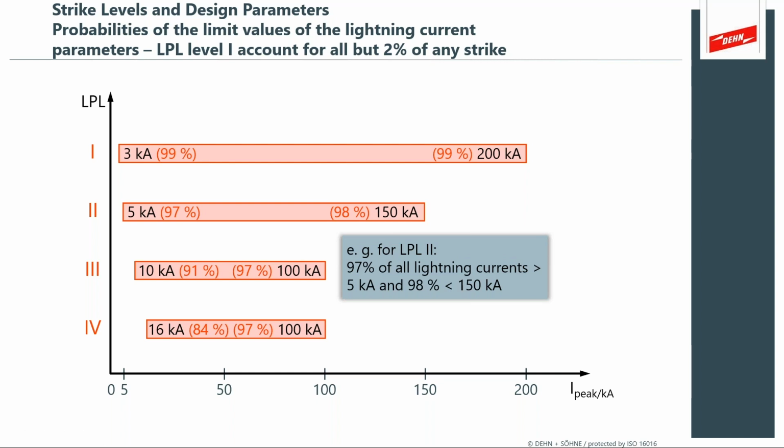And when we look at studies from places like Vaisala and StrikeNet, they identify the lightning characteristics as a storm moves through, and you can actually see the whole population of lightning in a given storm, and you do see lots of low-level lightning. So it's really important to understand that, because it drives the rolling sphere radius that's used in your risk control.